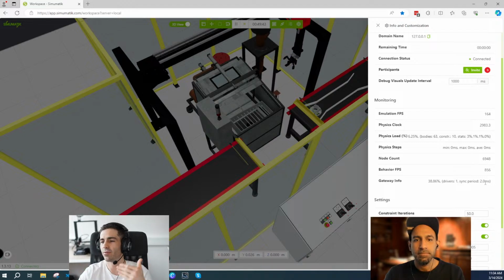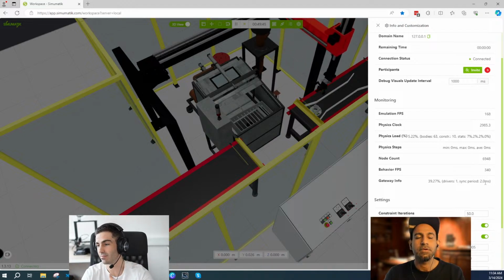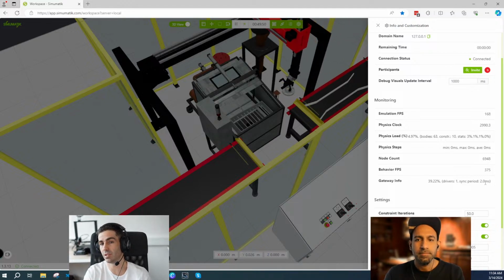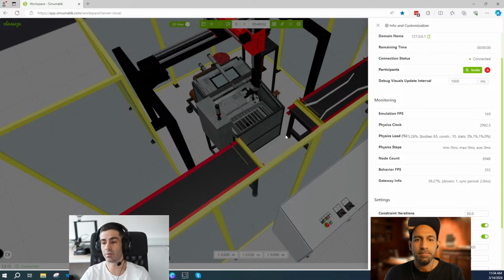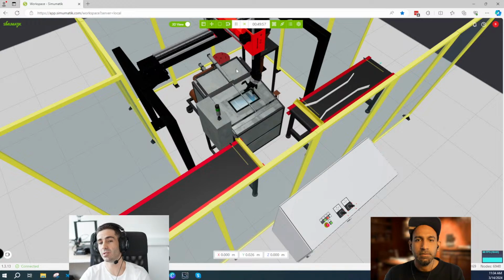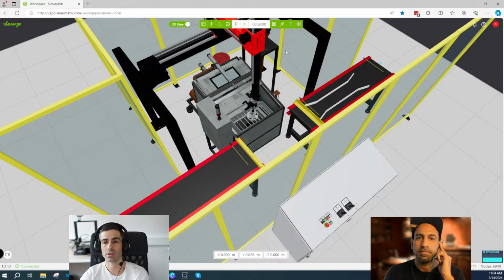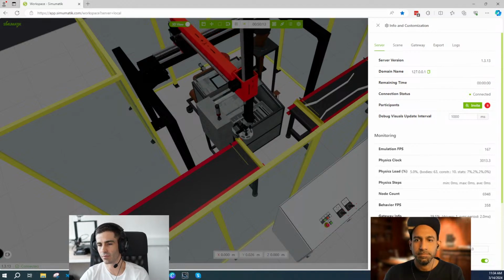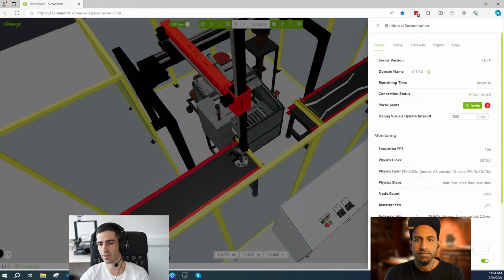Now, different drivers have their timing. So in my experience with this Omron driver, it was pretty quick. So probably we could change the parameters in the setup of the drivers and reduce the RPI maybe to 10 milliseconds and see even smaller steps in the graphs. Okay, so probably it is doable. And now I have quite nice numbers in the physics.